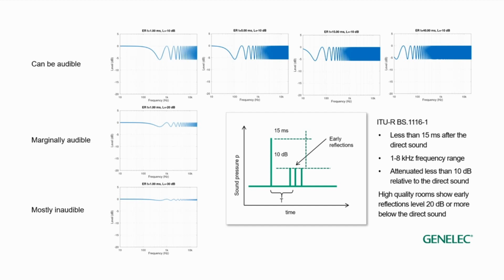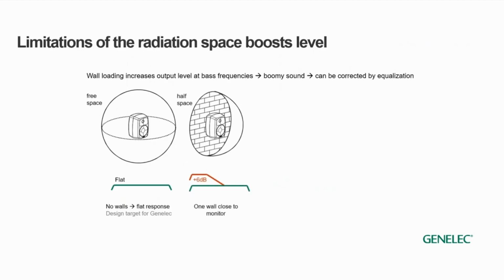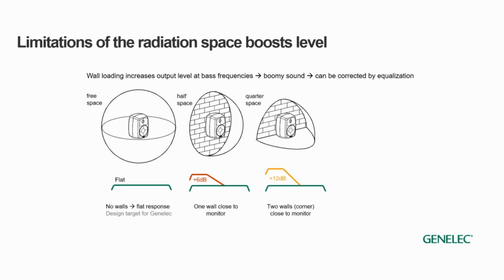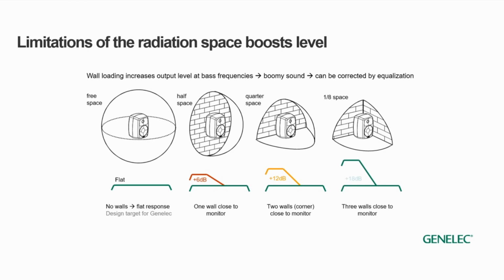GLM AutoCal can show you all of these effects in the frequency response, and GLM AutoCal can also offer you compensations for this. For example, when you have a significant reflection from a large desktop or working surface, GLM can find out the sound influence and can compensate for that. When you place a monitor close to a wall, there will be a buildup of level at low frequencies, and this will change the low frequency emphasis.